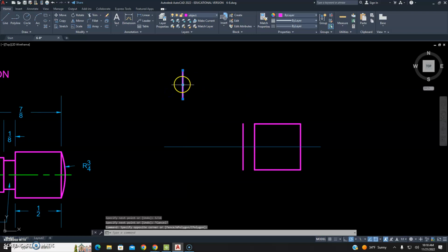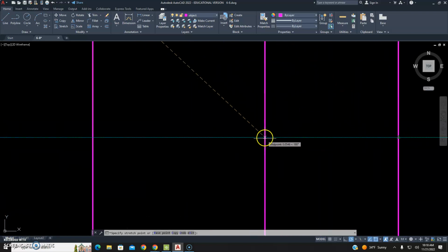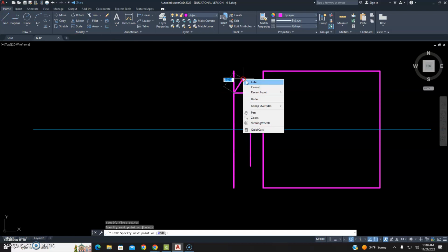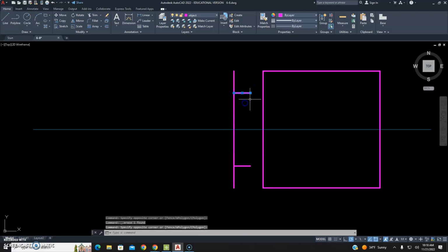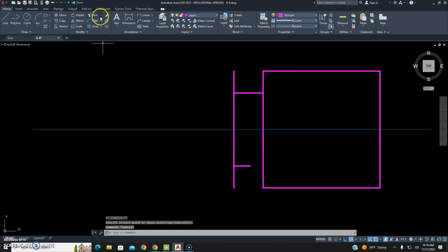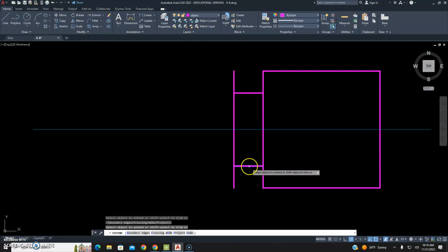And in fact, we don't even need to replace that line. We can just pop this right in here, at the midpoint of that line, so we're symmetrical there. Then we'll draw our top and our bottom. And then we can delete this because we don't need that anymore. We can just stretch these lines over. You can also use the extend command, which is the opposite of trim. You go to trim, click on extend, and then hit enter once, just like we did with trim. And whatever you click on, it'll extend instead.